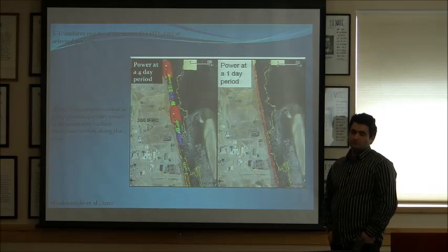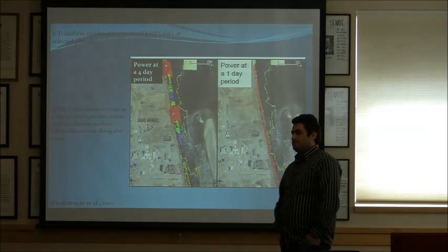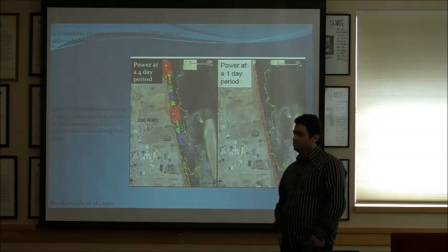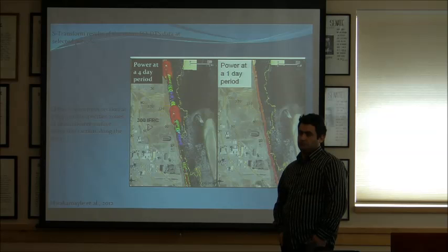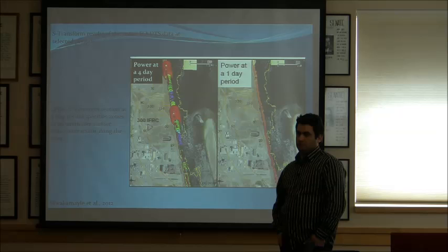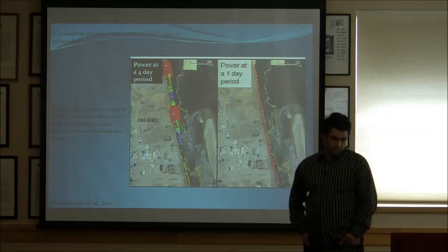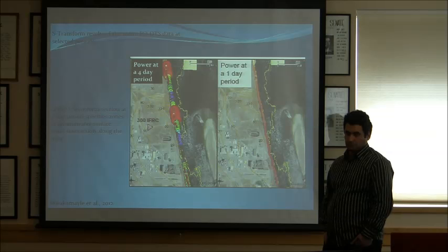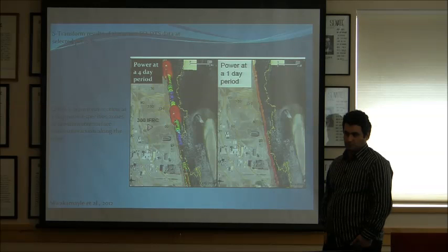In fact, lots of people have focused on spectral IP for NAPLs and contaminants, trying to use it like a gas chromatograph to tell you what contaminant is in what area. But from our end, there's also an IP response just in water and pore space, and constricting the pore space can give an IP effect. That's more the focus from a hydrogeologic standpoint, so we're going to have a little less ability to do that kind of work.